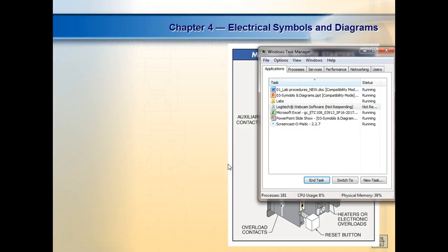And the way they had to hook them up is everything was hooked up to terminal boards. And for some reason, people don't understand how to use terminal boards. They either strip the screws out, right? You understand? Usually what happens, they strip the screws out. So what we decided to do was go to another technique where we go ahead and put what we call banana plugs under the